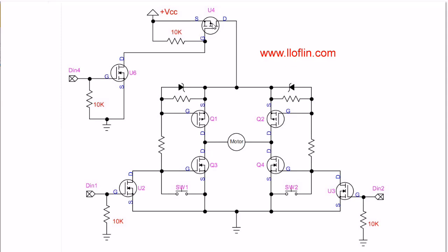While the motor power is off, I change direction whichever way I want to go. So if I want to reverse direction, I'll simply put a high out either on DIN 1 or DIN 2. Then I will reapply the power, and off the motor goes.